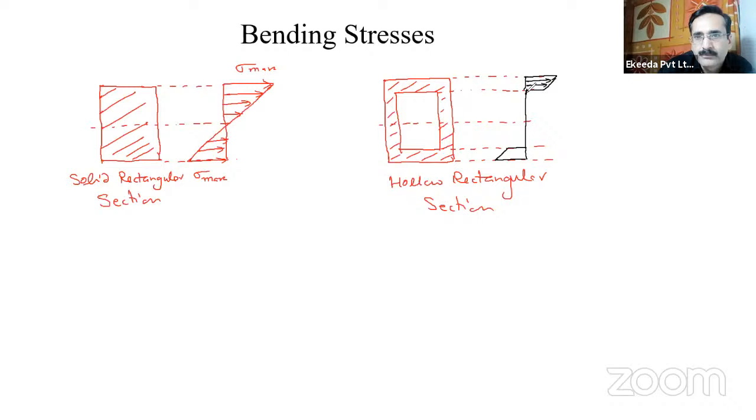This part. So this is the curve for bending stresses, and inside there is no bending stress, only a straight line, because there is no material, so no stresses will be developed, or stresses will be developed at the outer fiber only, and here at the outer fiber this will be sigma max, maximum bending stress, right? This is the case for hollow sections, right?